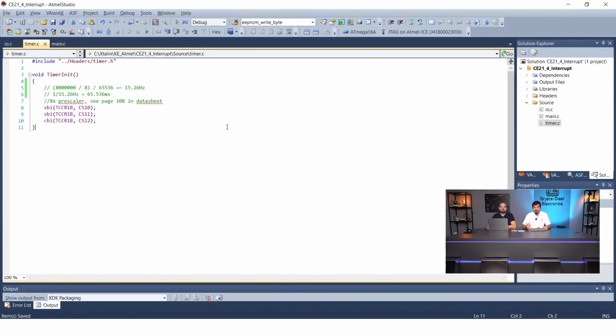This causes the system to detect only the first rising edge, because the other edges that are caused by the bounce will get ignored as the interrupt is disabled. The approximate 100 milliseconds set in the timer is long enough to stop bouncing, but it's small enough to almost always detect 2 consecutive intentional button presses.